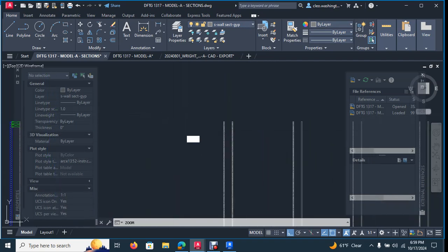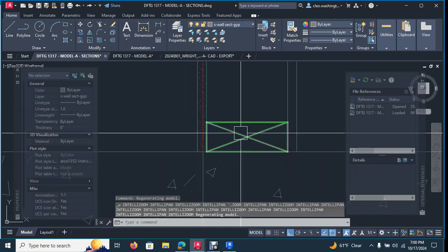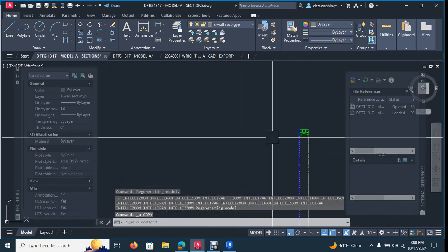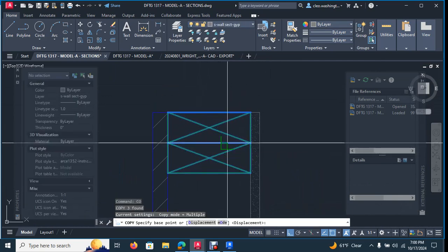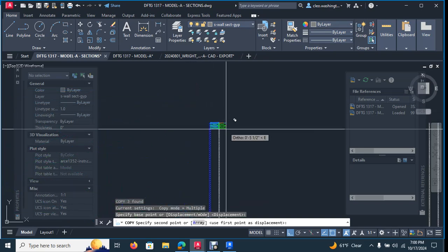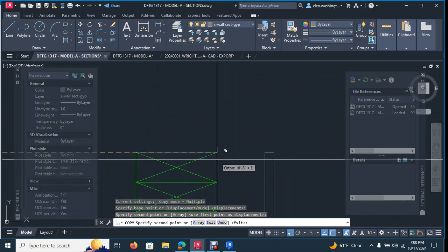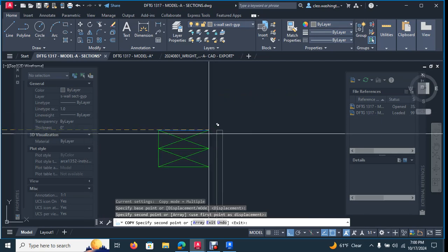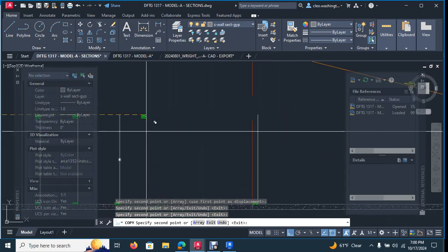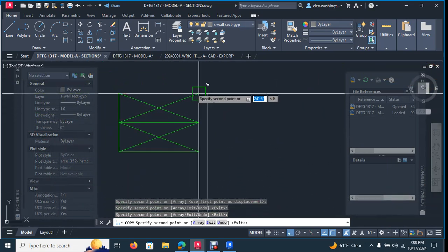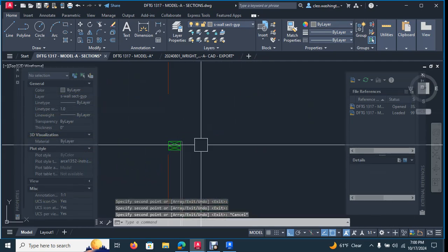All right, so once you have that, okay, what you do now is you carry over your double top plate. Your double top plate is going to be the same. So you right click and click copy. And you just copy this guy over. We forgot to bring some chipboard. We'll come back and get those. Apparently I didn't copy them. Just copy this double top plate over. And you'll copy this double top plate over here.